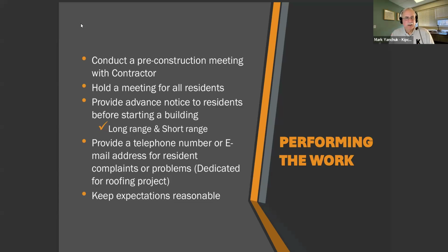On average, you could probably do one unit in a day. The crew sizes are usually 6 to 10. For the smaller crew, they could probably do 30 squares a day. A larger crew, maybe 50 squares a day. And for those of you who don't know, a square is an area measure that equals 100 square feet on the roof, so it's just easier to refer to it as a square.